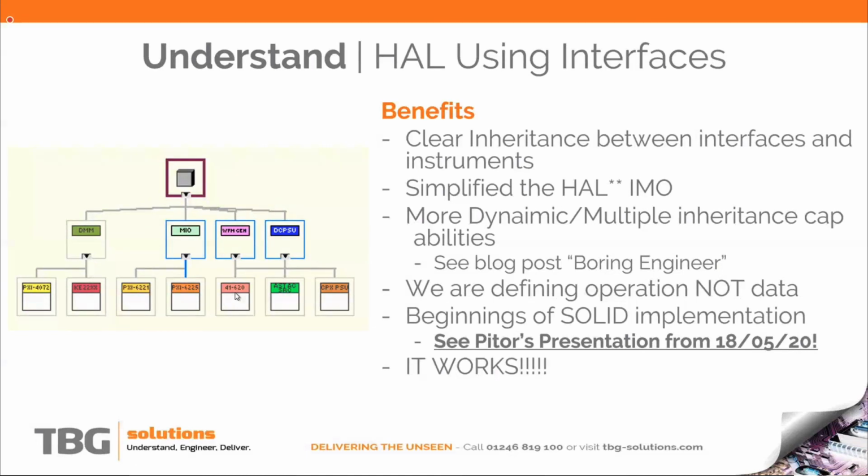So looking from a waveform gen perspective, a 41620 can output sine, square, triangle waveforms. So can the Asterion AC source, albeit through a different driver layer and different voltage levels. I think it's capable of like 500 volts, whereas the 41620 is 0 to 10 volts.